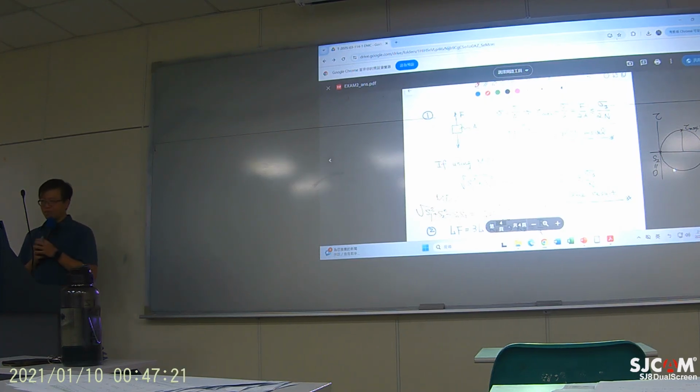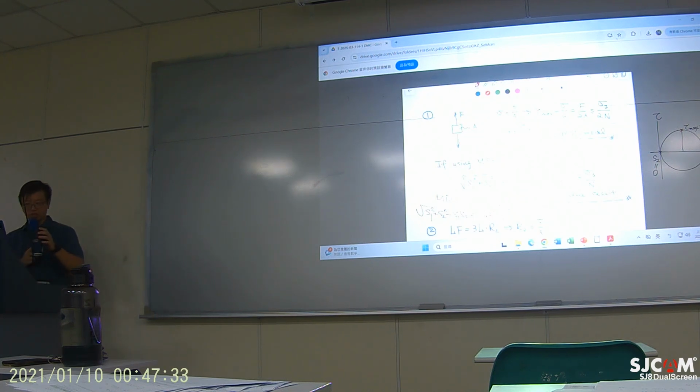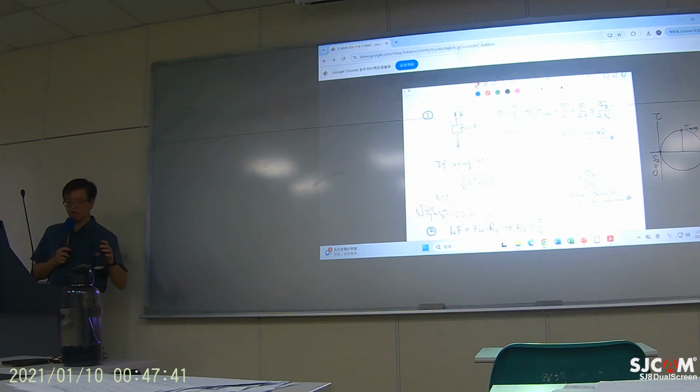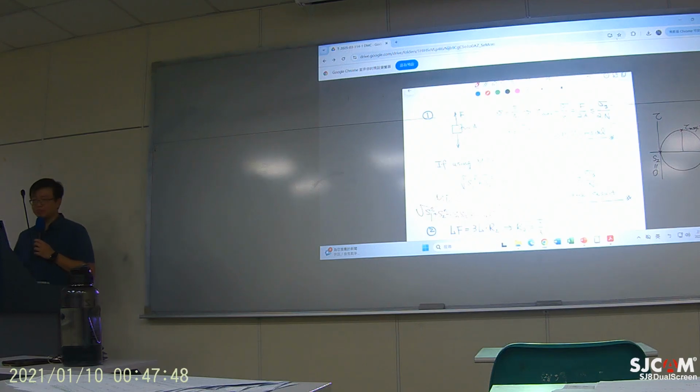And in the problem I said, explain why. You can say that because there's only first principal stress, second principal stress is 0. So in all three models, it ends up with the same equation. That's why the safety factor is the same. Okay, so that's a simple first problem.